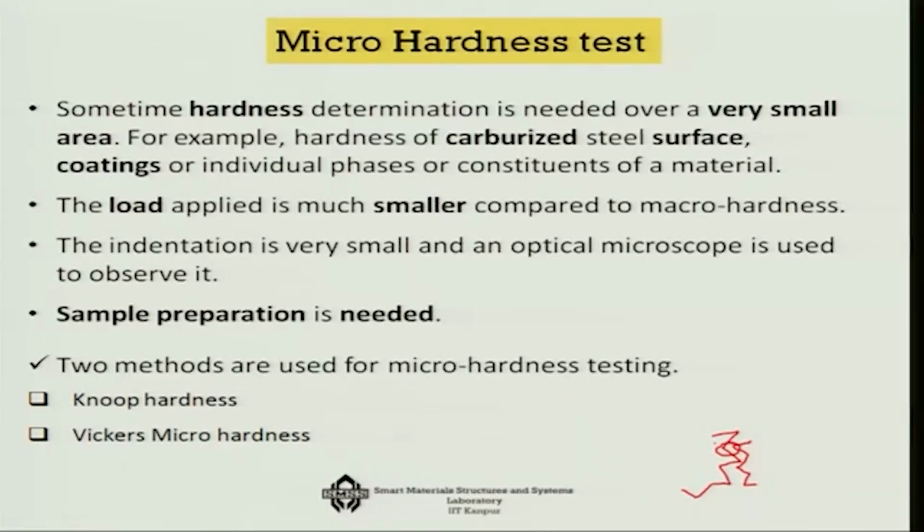Now, there is a continuous contact between the two. So, on this kind of surface, you must give a special coating on the teeth of the gear. You give a very thin coating layer which is very hard, to save it from wear and tear. This kind of very thin coating layer, you cannot really use the macro hardness tests for. You need a micro hardness test for doing it.